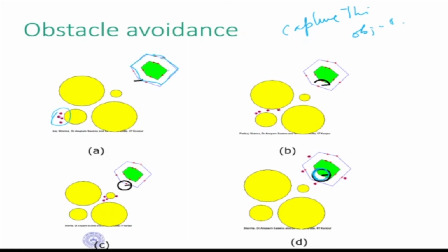So the first thing it has to do is find out on the expanded boundary where it will go and sit first, then where it will go and catch the object by using what we just discussed, optimization. So from the optimization, the answer would be that the robots need to go and sit on the boundary first, here, here, here, and here. And then on the object itself, these are the points where the robot should go and sit to satisfy form closure. Then it is caught.